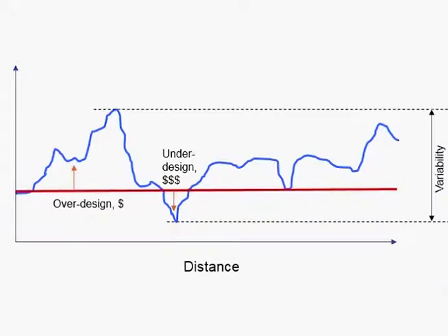And I've shown this slide before, but I think it's worth mentioning again. So in a lot of these projects, when we measure mechanistic parameters, we see a lot of variability. That would be the blue line. And we're seeing this in Iowa right now with our statewide calibration. Essentially, there's one number used, 150 PCI for modulus of subgrade reaction for the state. But there's all these different materials and conditions that exist. So on our projects, we're seeing this variability.